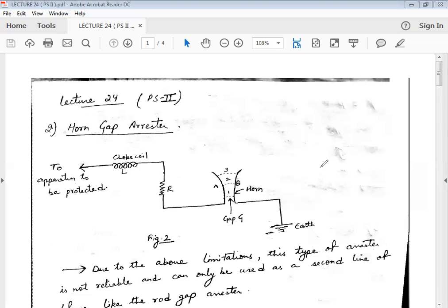The earthing screen and the ground wire protection scheme are not capable of providing protection against the traveling waves. So lightning arresters are mostly used to protect against traveling waves, which can cause serious damage to the equipment in the substation, such as transformers and generators in the power stations, and many other meters connected in the control room, if traveling waves reach their terminal operators.